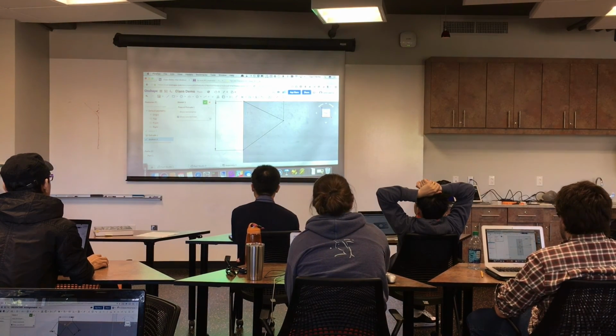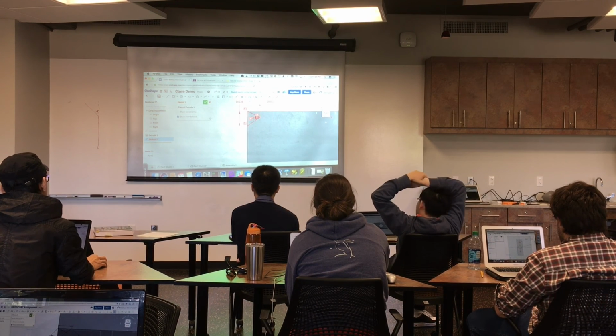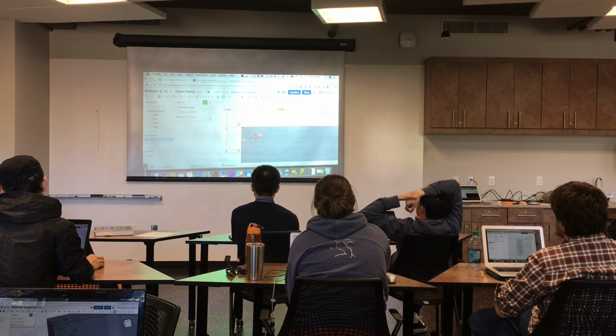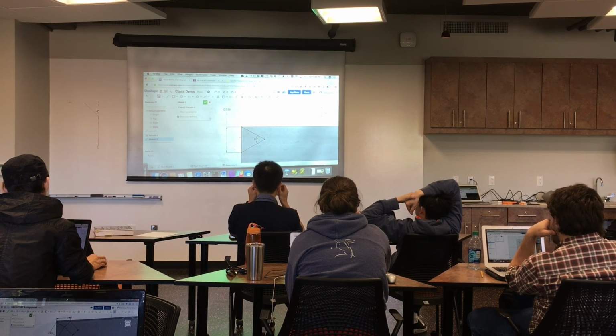The other way we could do this is by putting an angle dimension in. So between these 2 lines, I want it to be 60 degrees. But we still have a constraint conflict somewhere. And these are some of the trickier problems to figure out, unfortunately. All right, so if I delete that dimension, okay, so it can't be equilateral, right? Because I had it 0.8 deep. So now we're fully constrained.